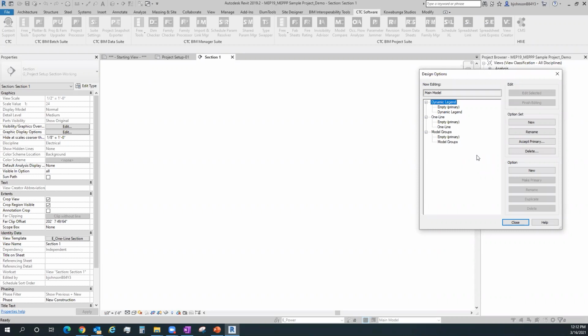Design options do not work well for multiple geometry types in systems. So that debunks that as an idea, right? We need to work fully within systems so they're all connected in one chunk. They can't be in alternate universes, which is basically what a design option is. So within our main model, our model groups that we would normally have in work sets, the idea behind the design option is that whatever you put into any other design option doesn't really exist.